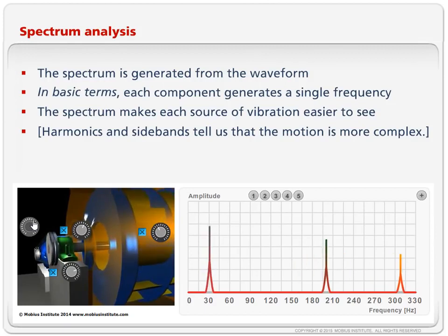Anyway, the reason I'm trying to do that, and not doing it very well, is that what we've shown here is this is the frequency, and I'm simulating this as if right now, that's what I was just trying to do with the knob, make it vibrate at 30 Hertz, because I've got 10 blades, so therefore the vibration from the fan would be at 300 Hertz. And the better way to say it is, well, this is 1x, 1 times the running speed. I've got 10 blades, so this peak would be 10x.